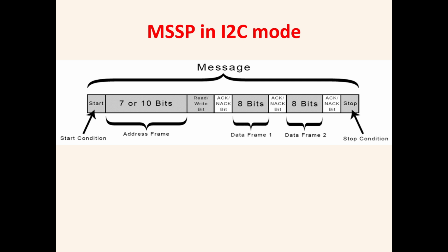This is more detail for the I2C protocol: what the packet contents and size could be. Every time you want to transfer your data frame, multiple data frames can be attached in your protocol, but the size of a data frame has to be 8 bits. For every data frame, an acknowledgement or no acknowledgement bit is appended.